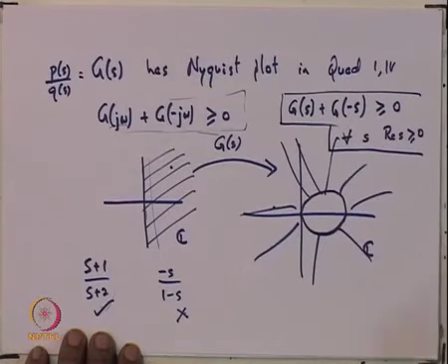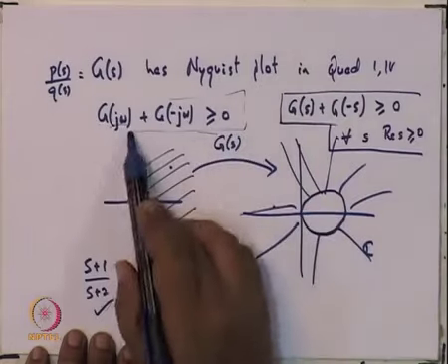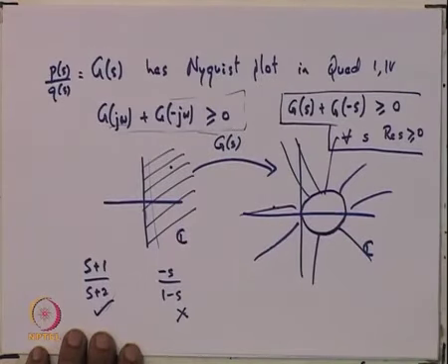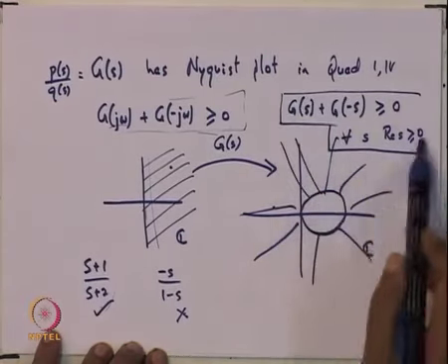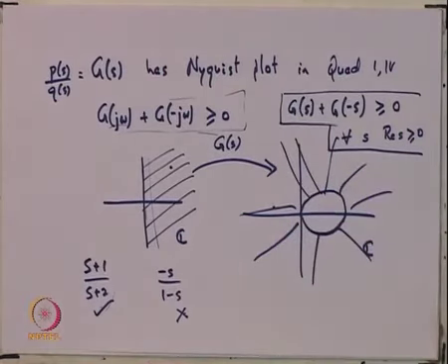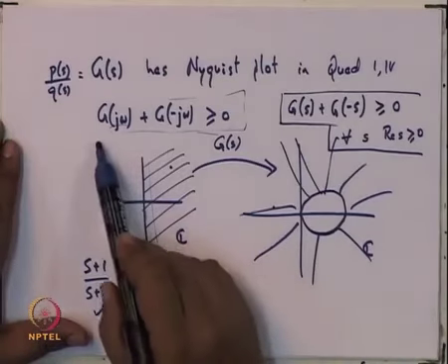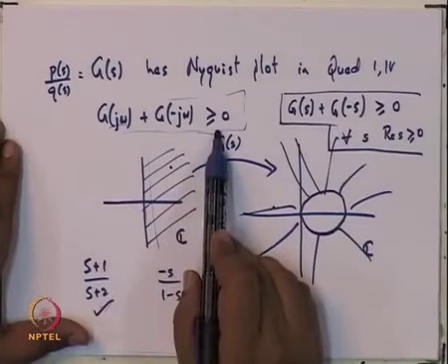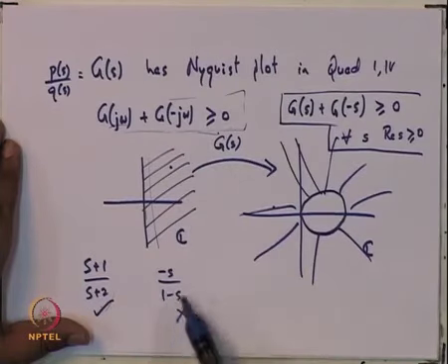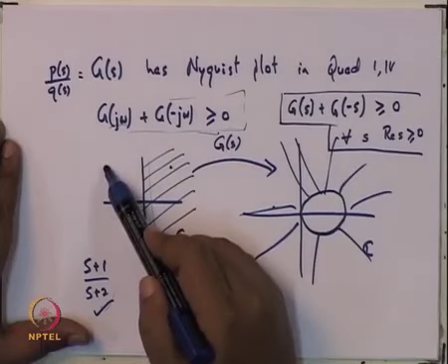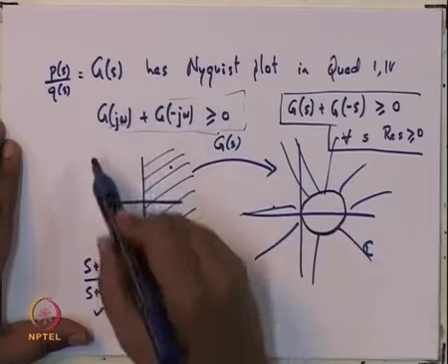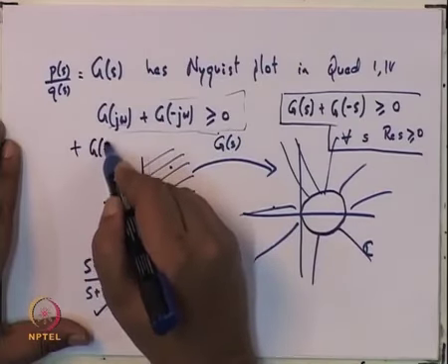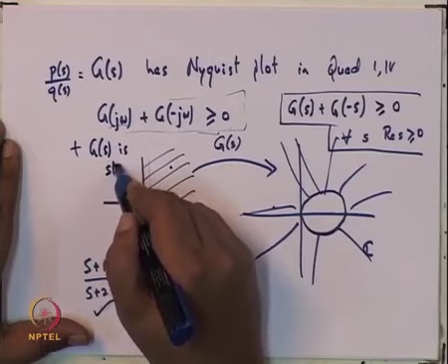But for historical reasons, this is usually given as the definition for positive realness, and there are some places where this definition is used. But if you give this definition, then such functions are also permissible, and to disallow these functions, the additional condition that is given is that this condition holds plus G(s) is stable.